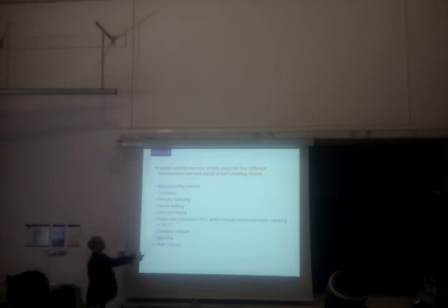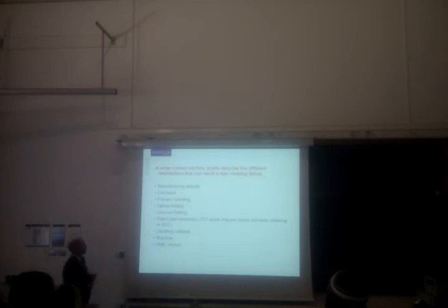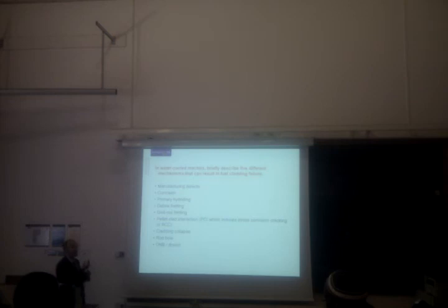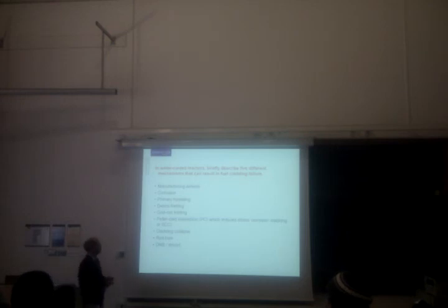Sometimes cladding collapses, a particular instance of a manufacturing defect. It occurs when, for various reasons, we have a gap in the stack of pellets. The cladding can collapse into that gap. We get very high strains around the edges of that collapsed region, those plastic hinges, and the cladding can fail in that way.